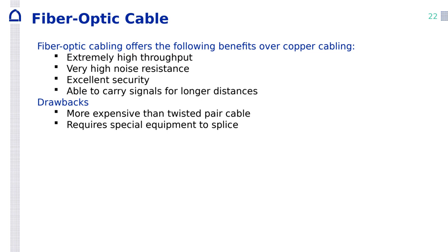What are the advantages of it over copper? First of all, high throughput, very high noise resistance, excellent security, and it can travel for long distances. What are the disadvantages? Of course, it is more expensive and it requires special equipment and training for the technicians. Okay. Any questions?